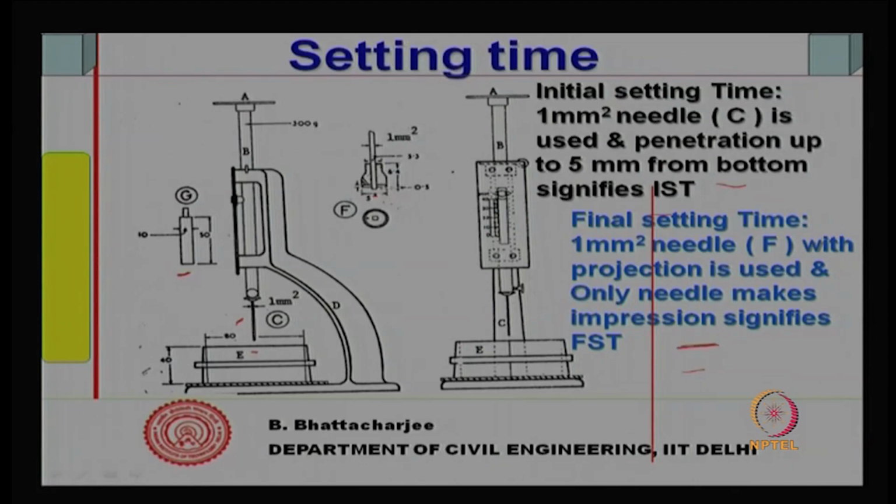That is called final setting time. So, when this tip is penetrating and this end does not leave any mark, that we call final setting time. So, this is how we measure the setting time, and this is the concept of setting time of cement.